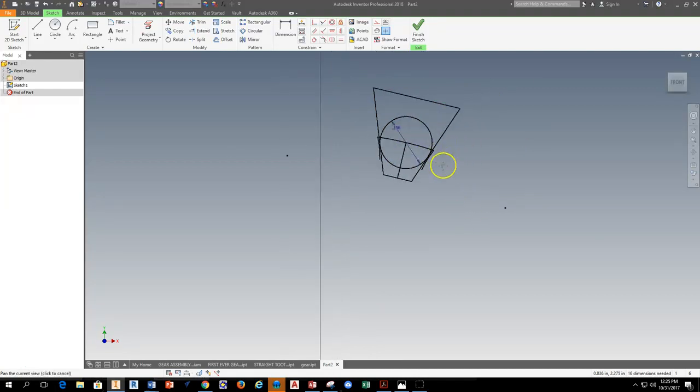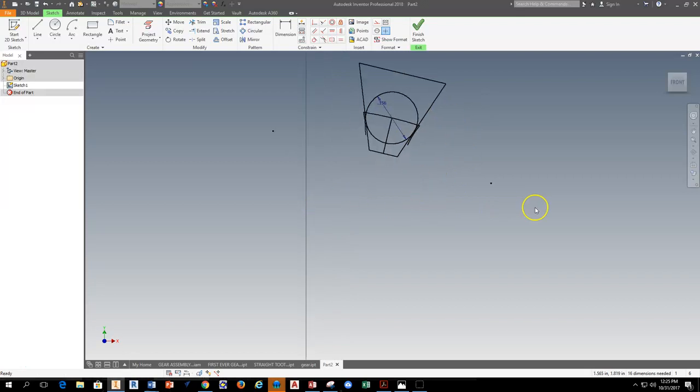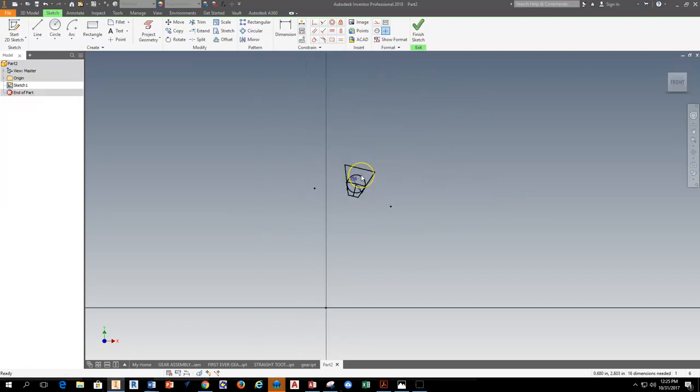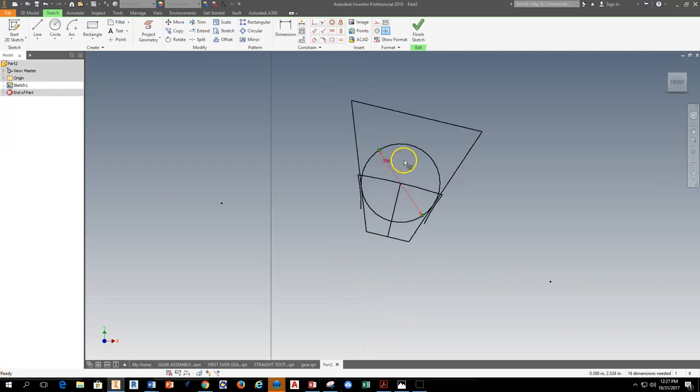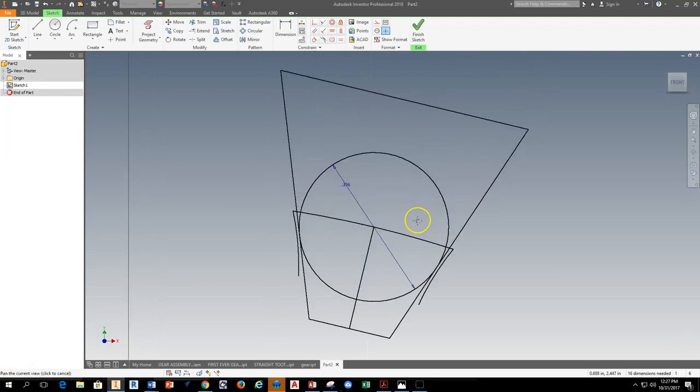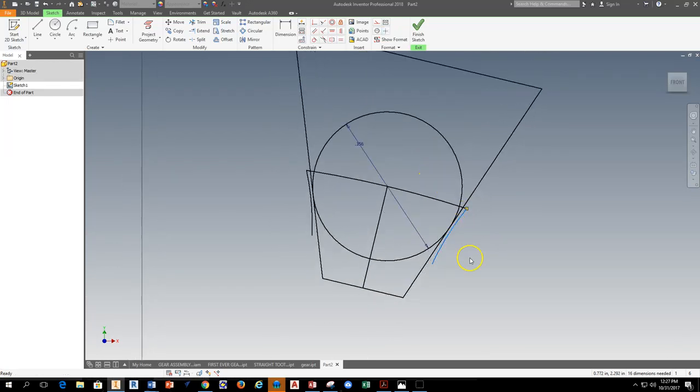The first thing I'm going to need to do is probably flip this thing around and get it lined up. I don't have any other extrusions to start working with here, so I probably want to get something extruded as a long bar stock that I can start working with. With the gear tooth in the new file, if there's geometry that came with it from your gear, like this arc, that's part of, I believe, the flank of the other gear.